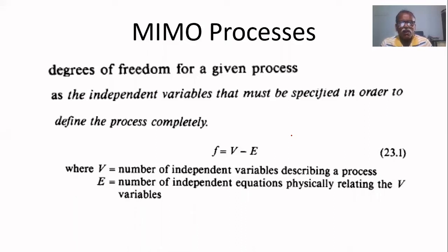Then the pressure inside and the temperature inside are also process variables. Because to maintain the quality, we have to maintain temperature and pressure inside the distillation column, and the top product vapor flow rate, the liquid flow rate and the bottom flow rate, all the four are manipulated variables.